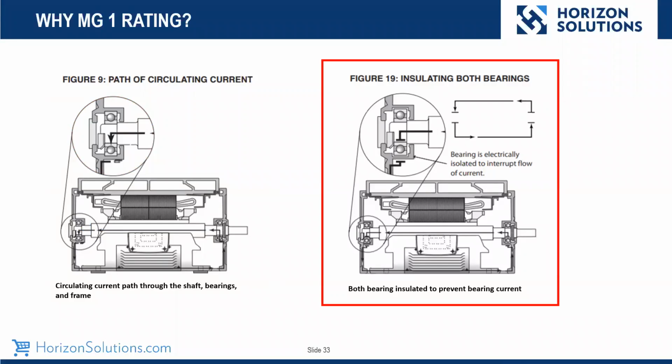What we do, it helps to put insulated bearings in here to stop this circulation. And what we want is the paint removed down at the junction box. We want a good, strong bond between the motor and directly back to the ground screw on the heatsink or the chassis of the drive, taking all the currents back and getting them to all cancel out at 0. This is a great way to do it. We don't want the circulation through the shaft and the bearings because obviously from the slide you've seen before, it causes some significant damage. Next slide.